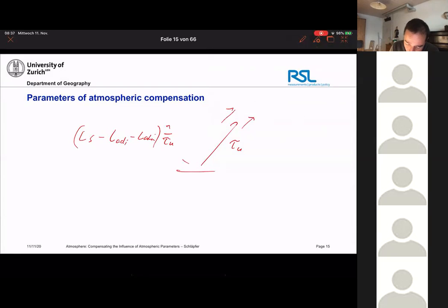On the ground, we had these irradiances. We had the EG, and this irradiance on the ground was the addition, as I did last time already, of the diffuse and the direct irradiance on the ground. So you had this E0 times cosine phi. This is the direct irradiance plus the diffuse irradiance, E diff,